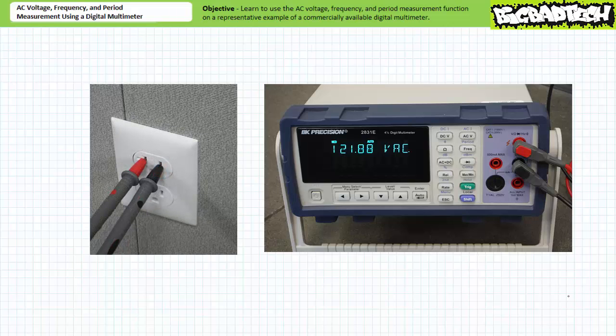If we swap the location of the leads, note the DMM still measures an effective differential of 120 volts. This is to imply that polarity is of little concern for an AC voltage source, since voltage regularly swaps polarity. The hot connection has an effective differential of 120 volts with respect to the neutral connection, just as the neutral connection has an effective differential of 120 volts with respect to the hot connection.